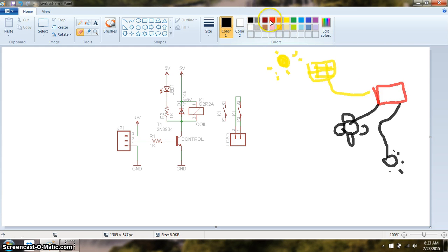Let's say I have this much charge left. According to how much charge is left, we'll keep some of them on. Let's say we'll keep the fan on. We'll keep some of the appliances on, and some will be off. So this is basically a demand side management system. The idea is this particular small circuit is going to help us do the automatic turn on and off controlled by a microcontroller.